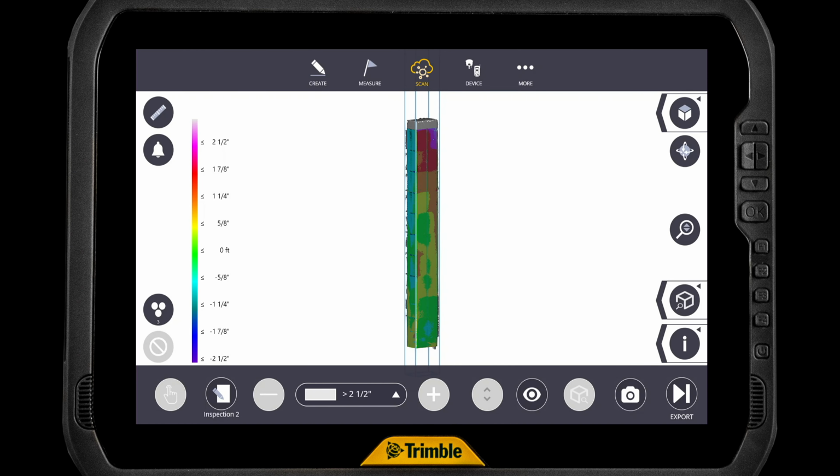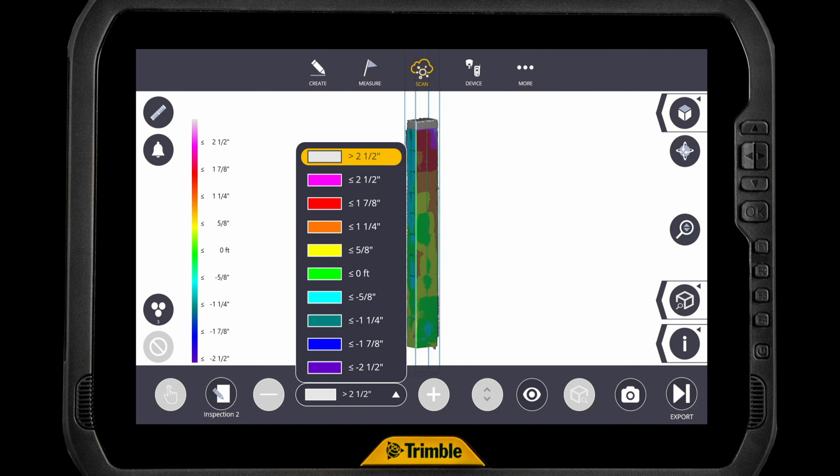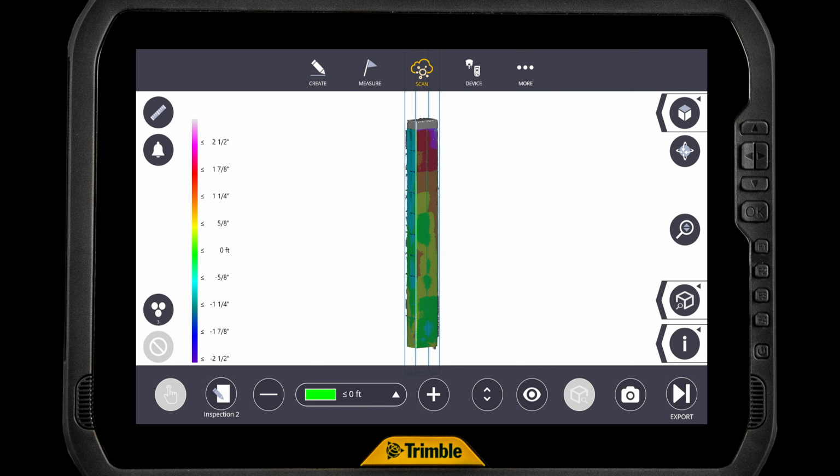Okay. Yeah. And after we've done that, we can use this little drop down here, or in this case, drop up, to change how we're looking at that scale. So if I go here to 0, and then I can go up or down to change that range. So if I start to give it more, instead go from a 3/16 up to a quarter, you'll actually start to see that green area growing there, because now it's recognizing more as in tolerance than what we had before.